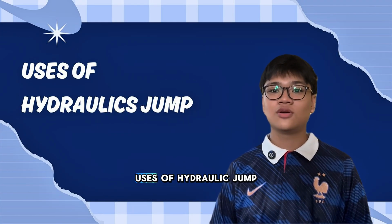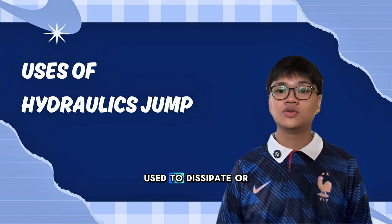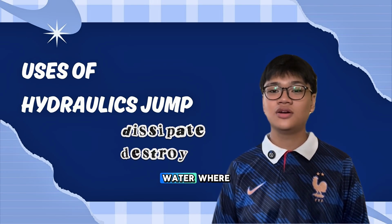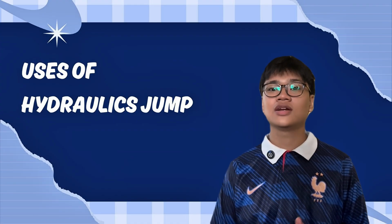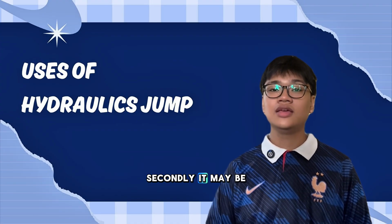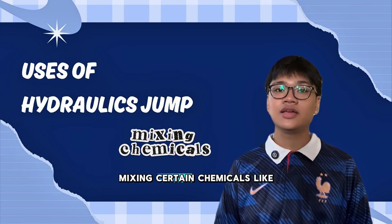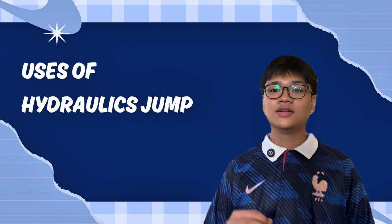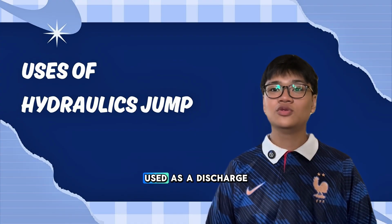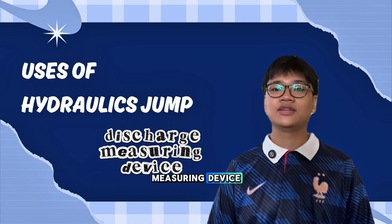So, what are the uses of hydraulic jump? Hydraulic jump is used to dissipate or destroy the energy of water where it is not needed. Otherwise, it may cause damage to the hydraulic structure. Secondly, it may be used for mixing certain chemicals like in a water treatment plant. Thirdly, it may also be used as a discharge measuring device.